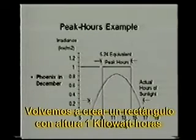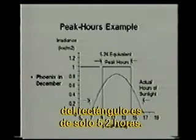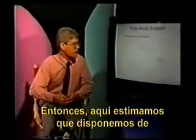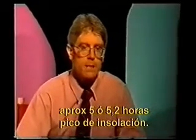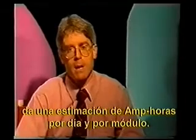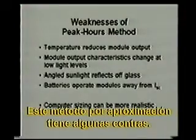We create a rectangle again with a height at 1 kilowatt per square meter, peak insolation, but now the width of the rectangle is only 5.2 hours, so that the area under the rectangle is the same as the area under the actual curve. So what we're estimating here is that we have roughly 5.2 peak hours of insolation available. We would multiply that times the peak current of a module to get an estimation for amp hours per day per module. This is an approximation method.